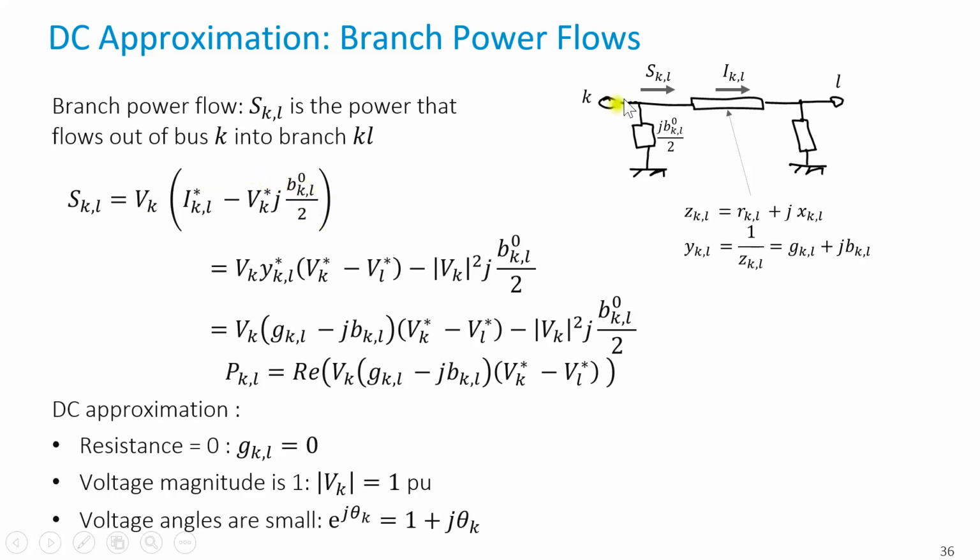The one that flows into, not the one that's injected, yes, the one that's injected at the bus here is given by this formula here, which as usual is given by the product of the complex voltage and of the conjugate of the complex current. We can expand this by exposing the various components of the impedance matrix that is given here.